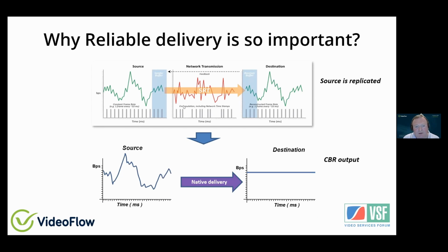Instead, what you want to do is take the source, natively pick up the feed, deliver that to the tower, but try to reduce the jitter and output that as a CBR output. Because it was conceived as CBR, it should be played as CBR on the output going to the exciter, so that the exciter buffer will not overflow or underflow, and you need to pace it.